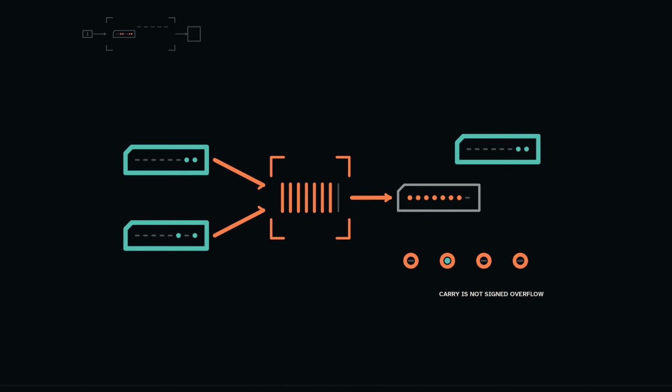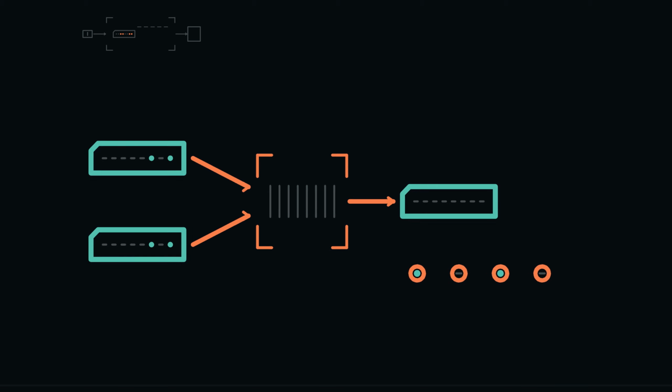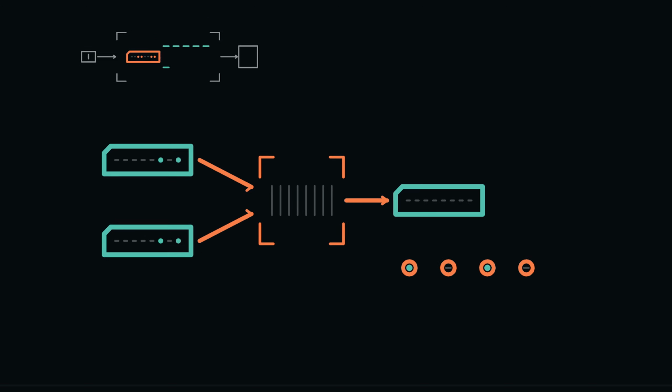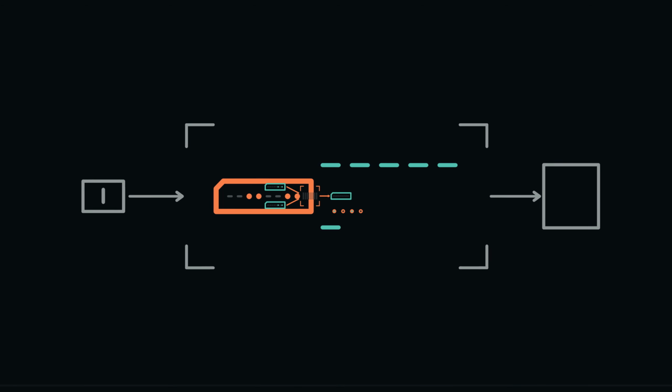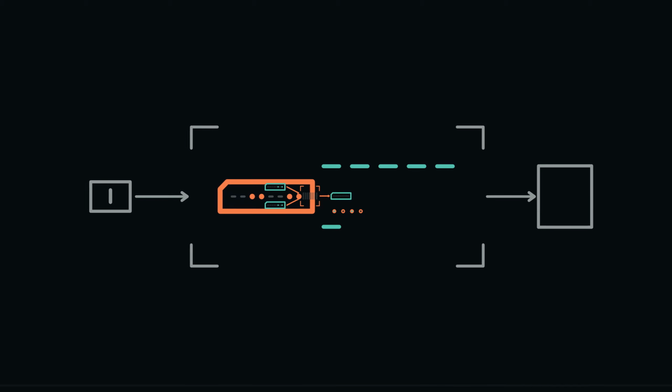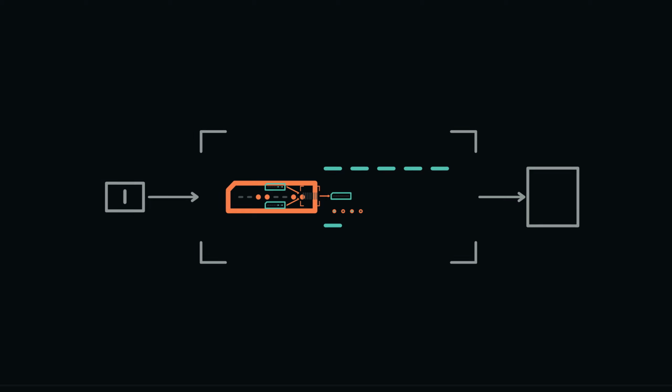Comparison prepares control to decide. It does not itself choose what happens next. The machine now has several certified transformations and 4 compact result facts. Bitwise logic stays within aligned columns. Shifts relocate bits within a fixed width and preserve the discarded bit in carry. Subtraction wraps like addition, with carry defined as no borrow. Comparison updates flags without replacing its source. Zero, negative, carry, and overflow retain distinct meanings.